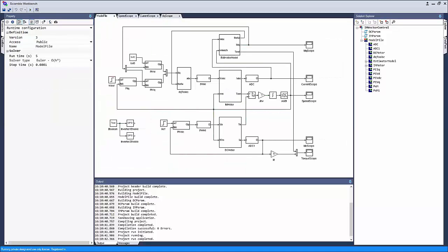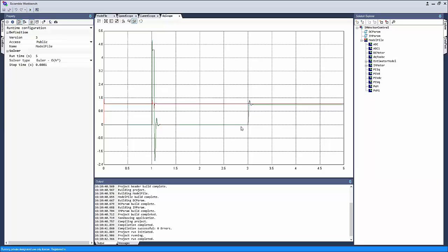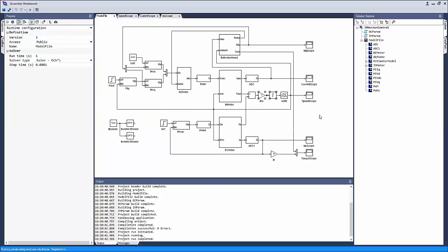In this particular simulation model, we haven't used 1 by Sj plus B, we have just used 1 by Sj. And hence you don't see a residual component in the current once the speed settles down at the desired speed and the load torque is 0. And the IQ current also goes to 0. To convert this simulation model into real time, all you have to do is add additional tools that can allow us to measure the currents and the speed.